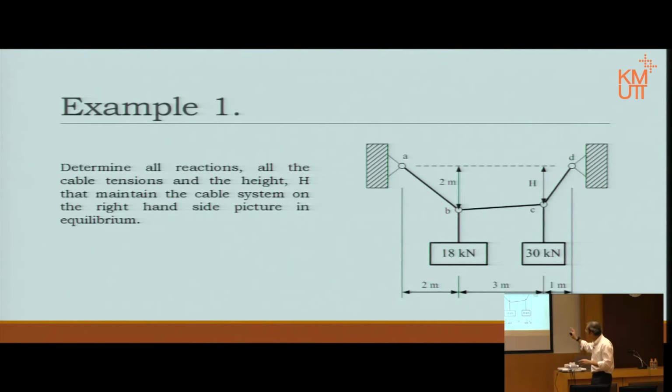Now, if we look at this picture, we should realize one thing. The calculation system, all of the conditions of the force system, is something that we already know. Basically, it has a pin support on both sides. Each support will have two reactions, as we already know. The circles A, B, C, and D are pin joint connections, meaning at point B and at point C, the cable can rotate freely. There is no resistance to that change in angle.